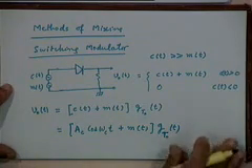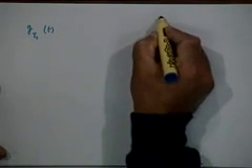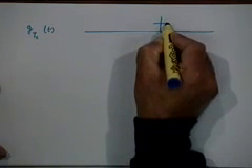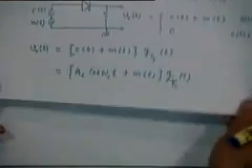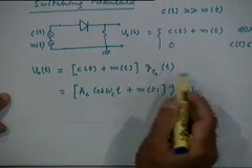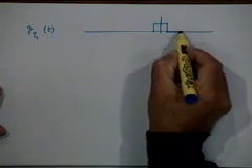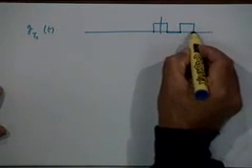Right, where g(t) at frequency f_c is a periodic waveform which looks like this. So for half the carrier cycle you are multiplying with 1. So g(t) is 1 during that half cycle. For the other half cycle it is 0, and then again it is 1, again it is 0, right.